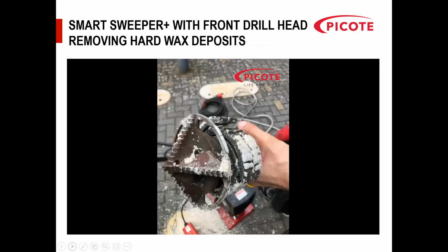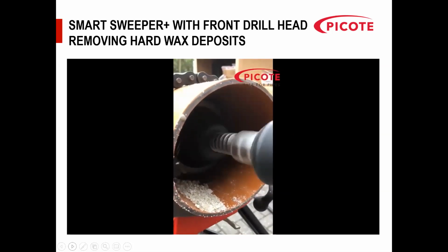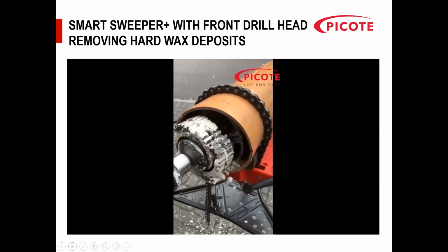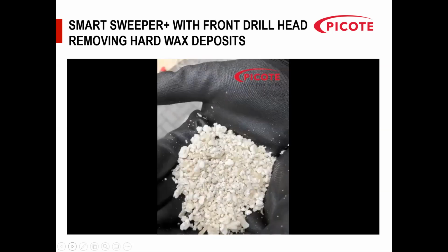So a little clip here. This is a job we worked on for a client, where they were looking to remove a hard wax deposit from inside the pipe. As you can see here, we've got the sweeper with the front drill head on. This is with the Power Plus, and as we push it through and put pressure on, it's cutting through, and the wax is coming out in little chips. This was on a 6-inch pipe, and we did the test work for the contract. You can see the size of the little pellets it was cutting it into.